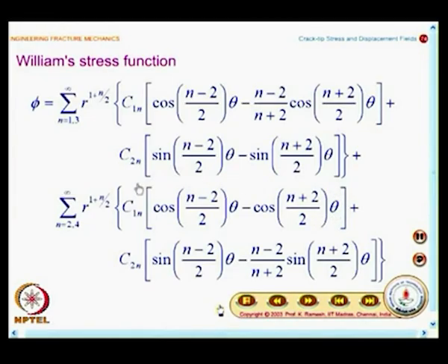So, that would be the second term of the stress function. Mind you, you are looking at the stress function, and we have also had some discussion about the forms of stress function. If you look at the form of this stress function, r squared multiplied by 1 minus cos 2 theta, it actually represents a uniaxial stress field in the x direction.